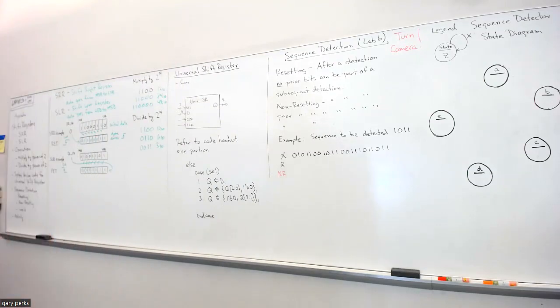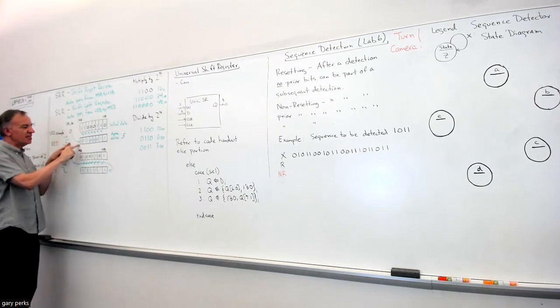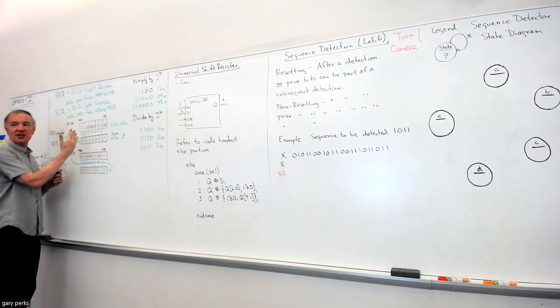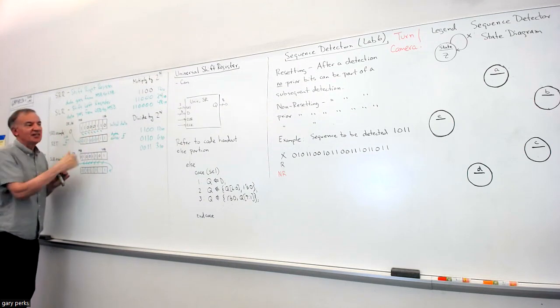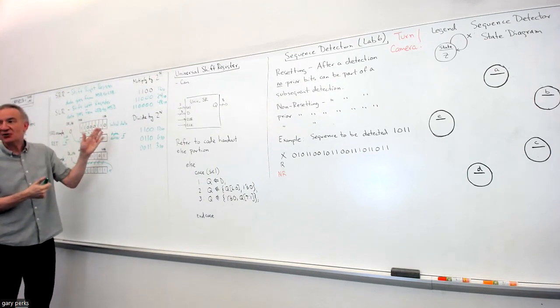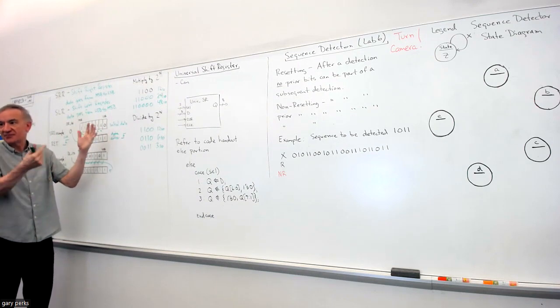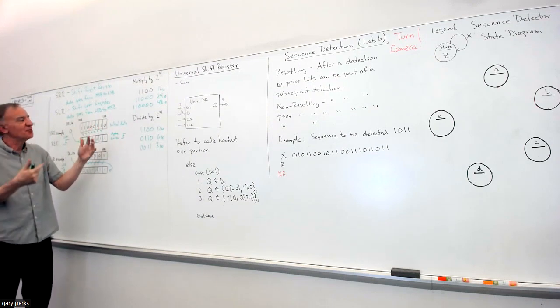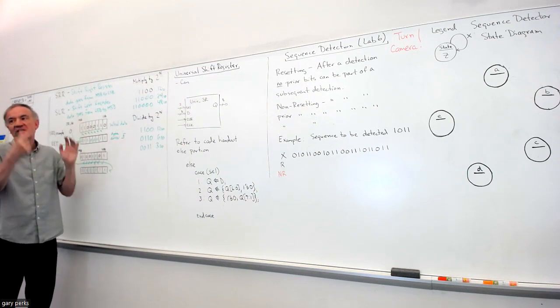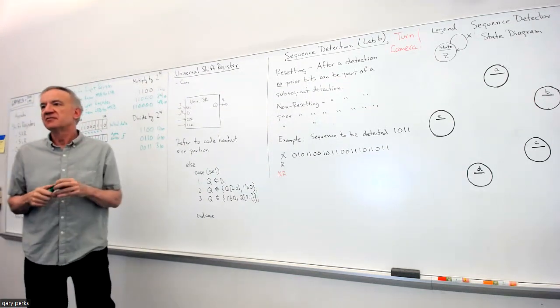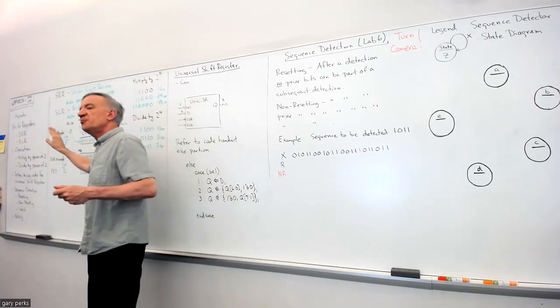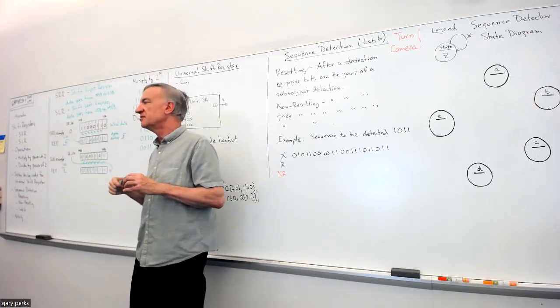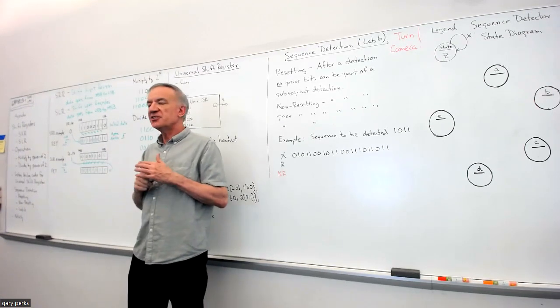So for the shift right register example, does it add an extra bit or does it just usually... It just shifts the bits one place. That's why it's called a shift register, because the new data comes in, but all the other bits that were there originally, they just move over one place. And then because there's no place for this bit to go, like there's not another flip-flop for it to get stored by, it just effectively goes away. You lose that bit. But it's just that all the bits just get shifted. Any other questions?